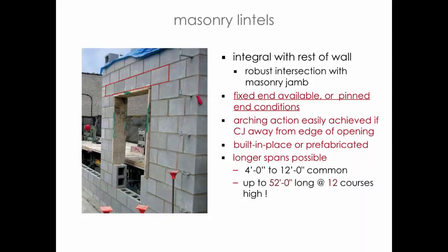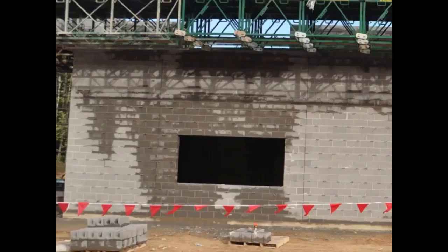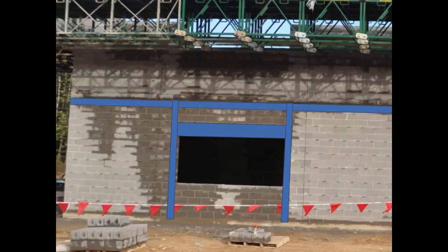Just like anything else. But again, showed this picture before, show it again. I mean, it's going to be integrated with the jambs around it. Just show a project that we helped with. Again, you have the lintel that spans over the opening that's crossing with those jamb reinforcement. One of the things that the contractors wanted me to talk about is the fact that you have grout in a lot of these locations.